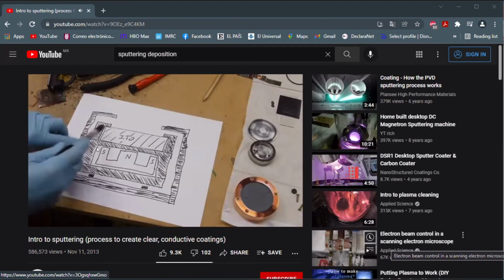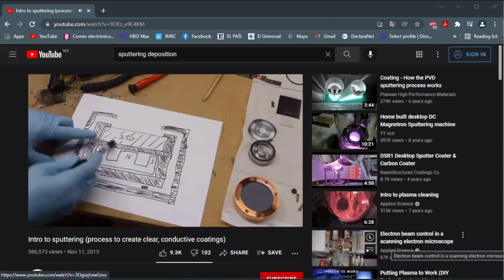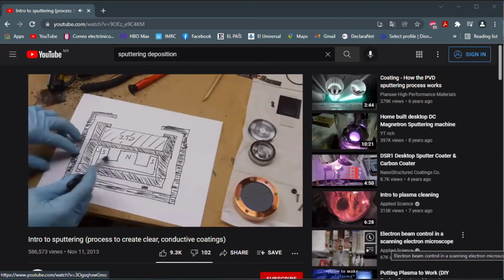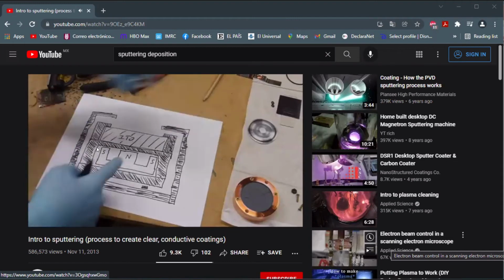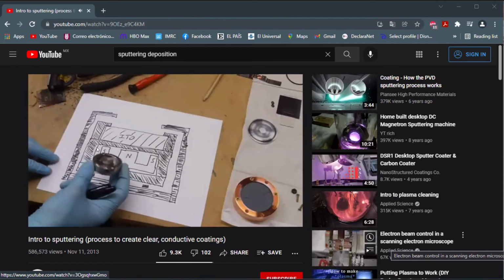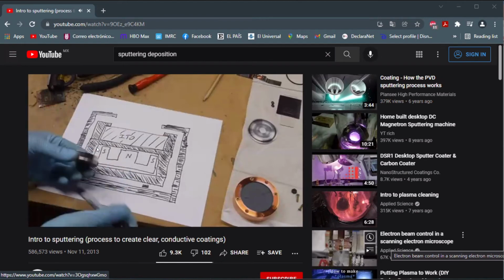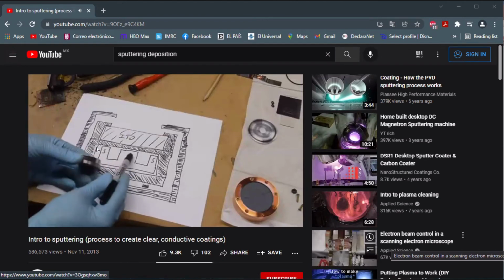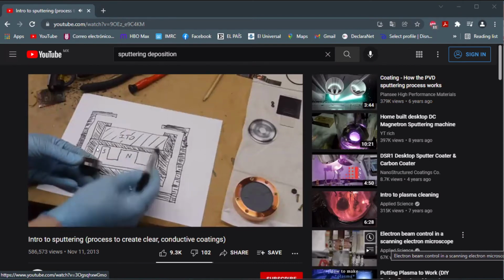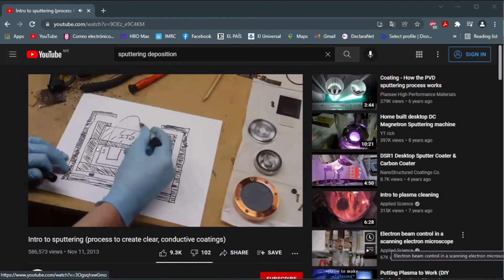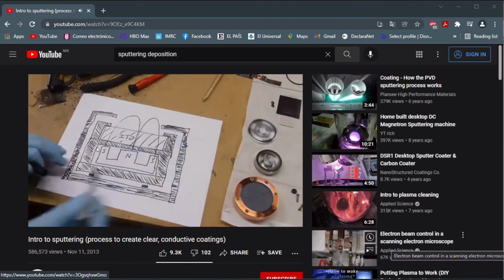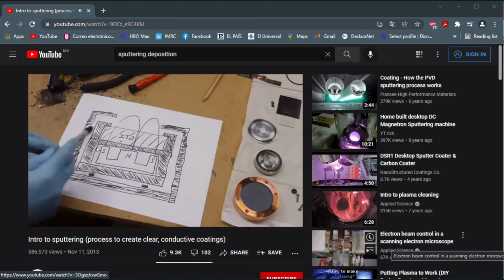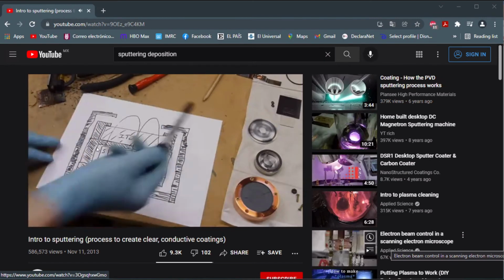So here's a cross-section view of the sputter gun. The ITO disc is the thing with which we want to make the coating. And then we've got our magnetic pole piece here with north and south poles. It doesn't matter which is which, I don't think. The idea with the pole piece being that the magnetic flux goes through the steel and then back up through here. So the magnetic field lines look like this. This whole intersection here is at about negative 1,000 volts, and the outer section is at 0.